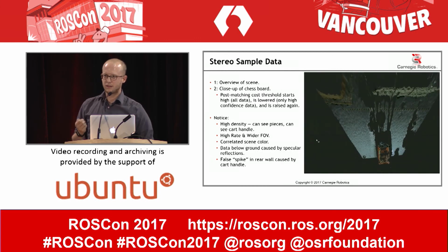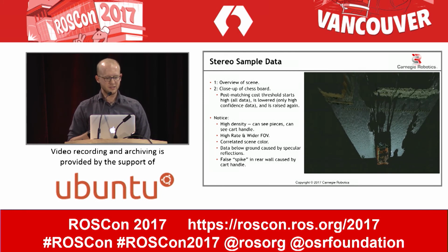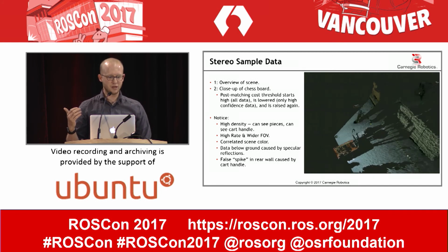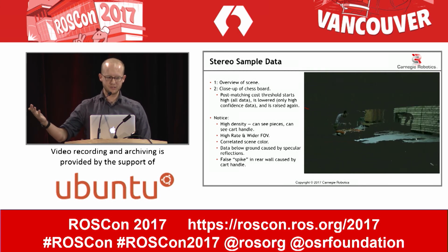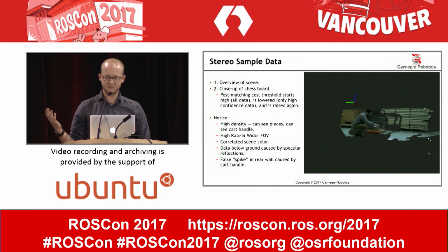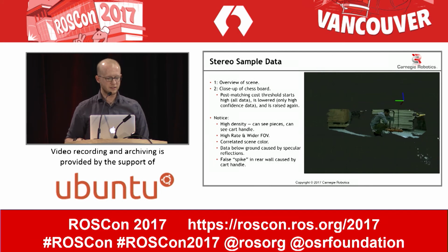This is the same data from a stereo camera. This is from the Multisense, the camera that we build. And you see that there's a lot higher density here, but you now start to have that range accuracy problem. The data close to the camera is much more accurate than the data at that back wall, which is 3 or 4 meters away. There's a lot more range variance on that stack of panels behind.